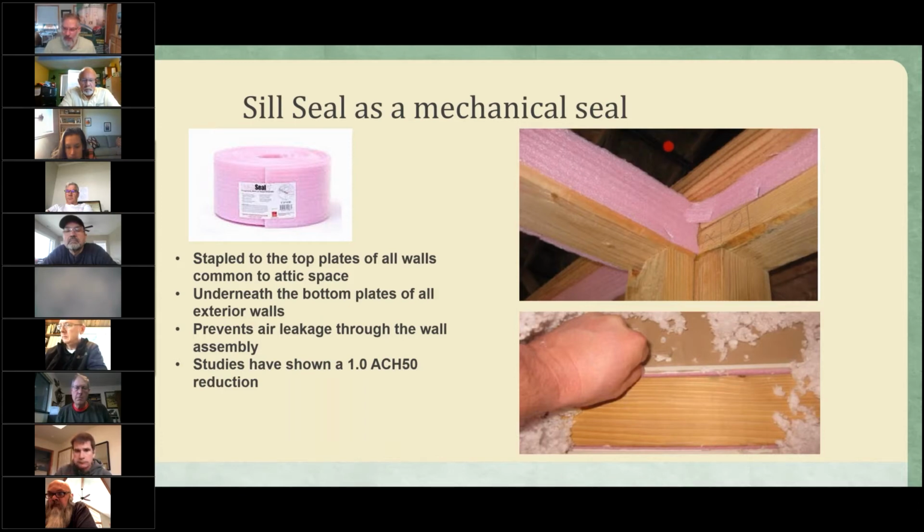What happens if you don't do that is the air from up here in the attic can get down in the small gaps between the wood and the drywall, get down here into the cavity of the wall, and then they come out through the electrical plugs and light switches. And it's a very common way for air to travel. You wouldn't think it would be much, but it makes a big difference.